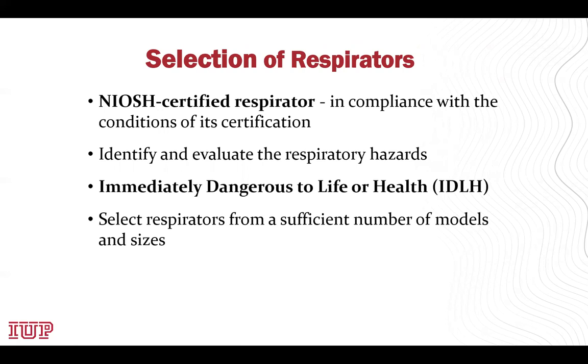More on selection. You want to select a NIOSH certified respirator that shall be used in compliance with the conditions of its certification. Identify and evaluate the respiratory hazard in the workplace, including a reasonable estimate of employees' exposure, identification of contaminants, chemical state, and physical form. Where exposure cannot be identified or reasonably estimated, the atmosphere shall be considered immediately dangerous to life and health. You want to select respirators from a sufficient number of models and sizes so that the respirator is acceptable to and correctly fits the user.